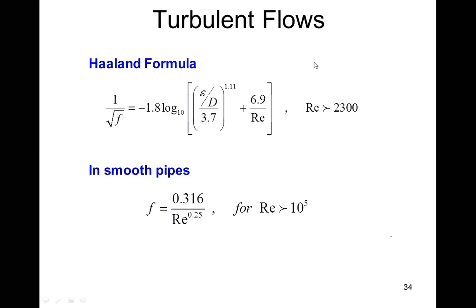So in that case, you cannot smooth any surface beyond a particular point. You can do all sorts of things, and those types of surfaces are called hydraulically smooth pipes. It means you did your best and you cannot control the roughness beyond that point, and those surfaces are called hydraulically smooth surfaces.